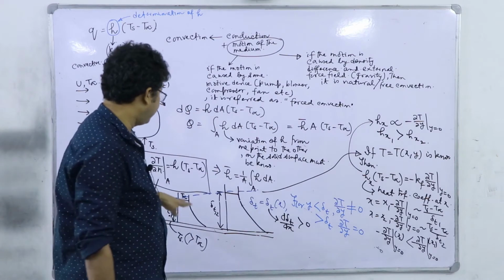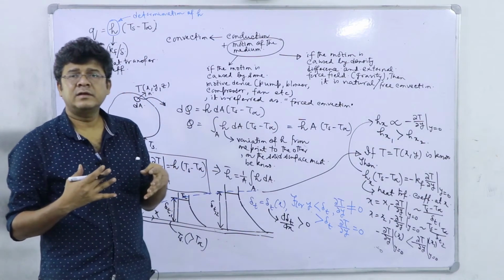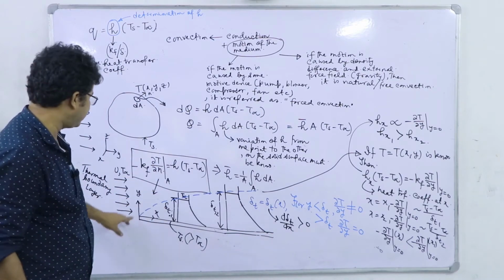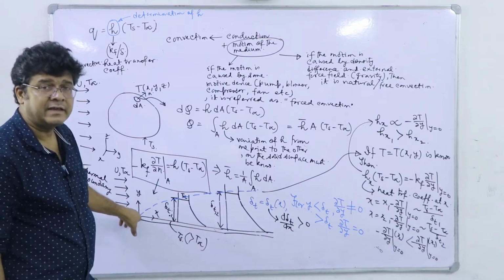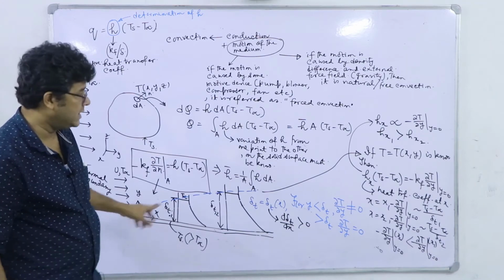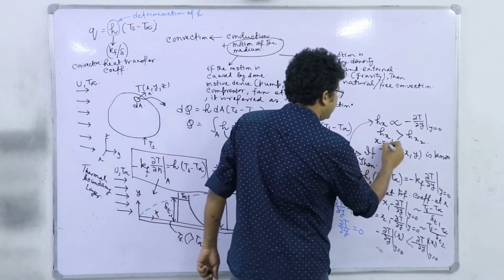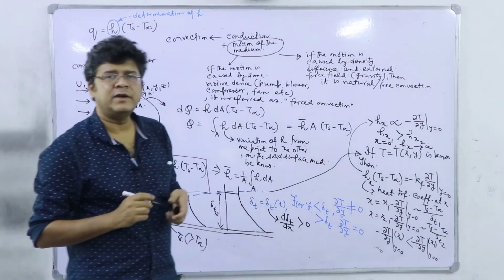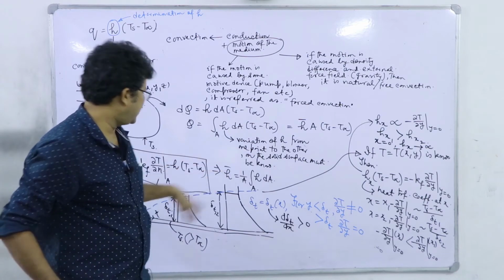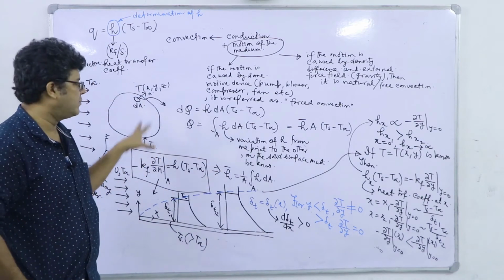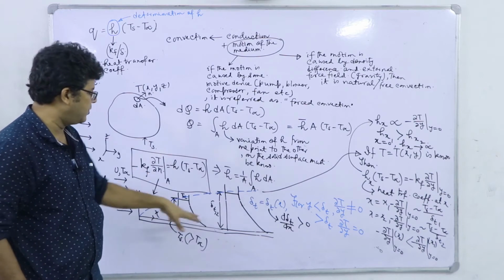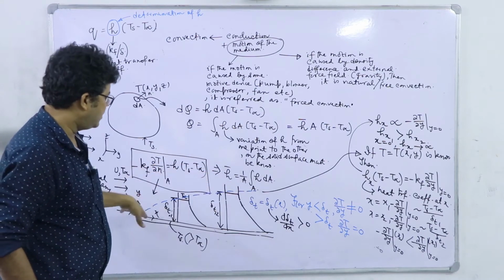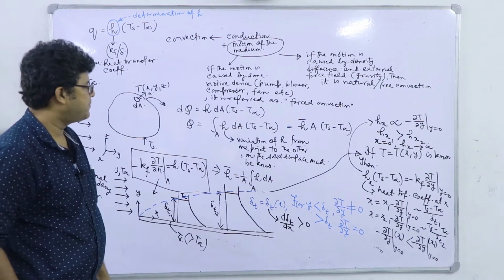And one of the very important consequences, though it is important from the mathematical standpoint, it's not important from the engineering standpoint: at this point where delta is equal to 0, Hx is actually infinity. So, at x is equal to 0, Hx tends to infinity. So, this is more a point of interest for the mathematicians, right, but as it is a point we are not interested in, we have to go for averaging this heat transfer coefficient over this entire length of the plate. Okay.